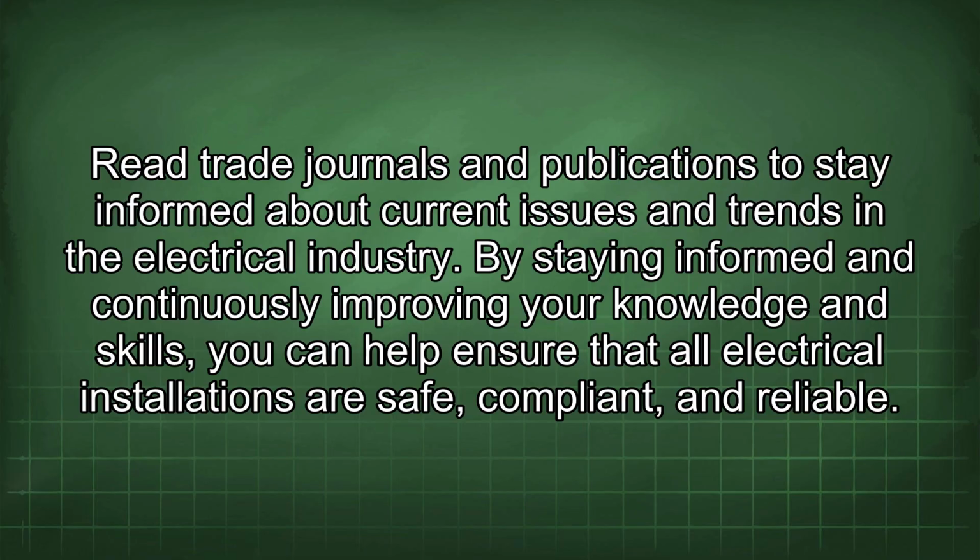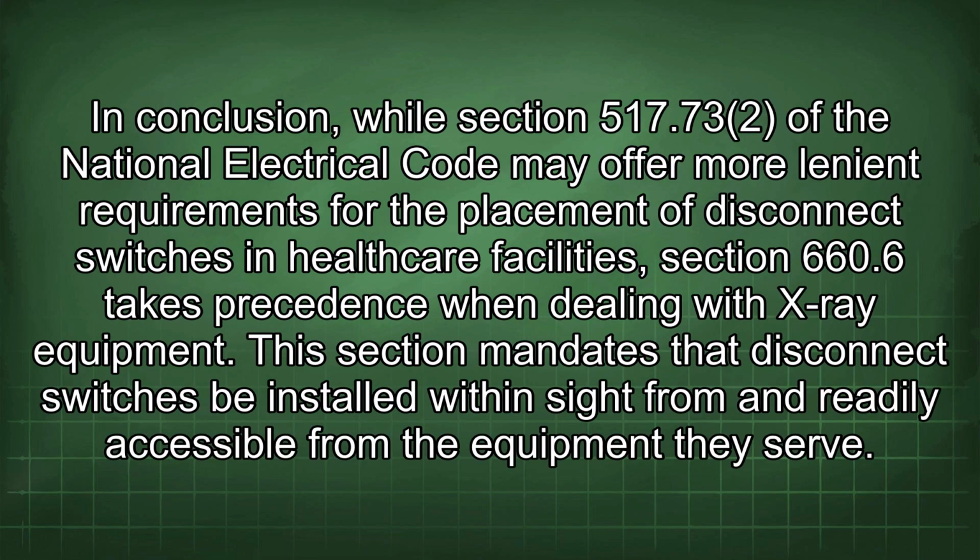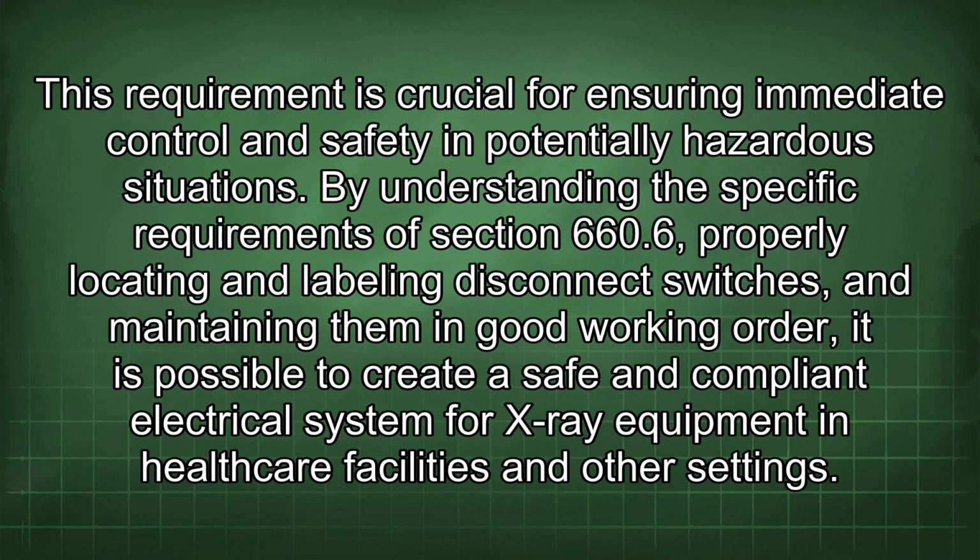In conclusion, while Section 517.73 of the National Electrical Code may offer more lenient requirements for the placement of disconnect switches in healthcare facilities, Section 660.6 takes precedence when dealing with X-ray equipment. This section mandates that disconnect switches be installed within sight from and readily accessible from the equipment they serve. This requirement is crucial for ensuring immediate control and safety in potentially hazardous situations.